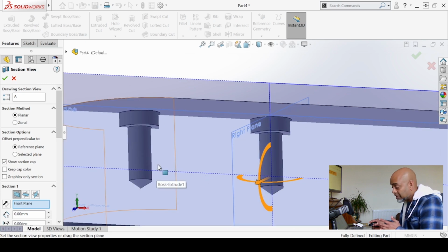Once again, these are industry standard, so if you were to go out and buy yourself M20, it will fit through here quite nicely, and that is 60 deep, really. So all of this, you don't need to worry about making sure this angle is correct, making sure that depth is correct, making sure that gap, none of that. It's all programmed in. All you've got to do is click on the right icon and click on the right plane where you want to drill.